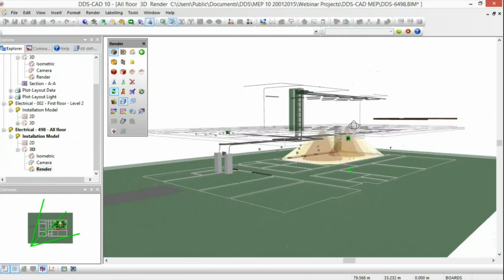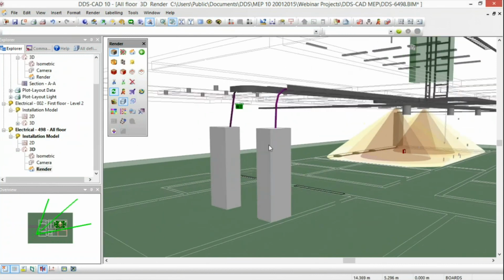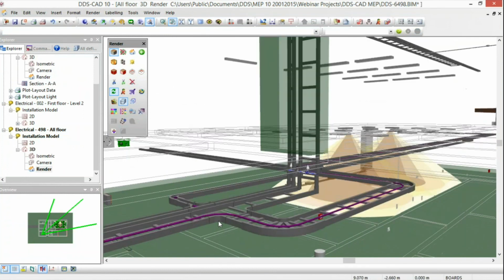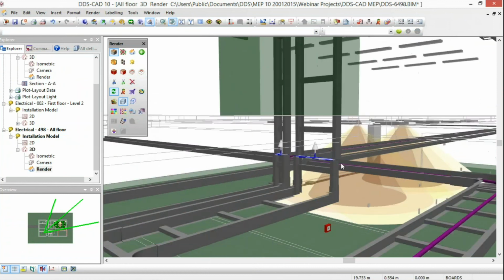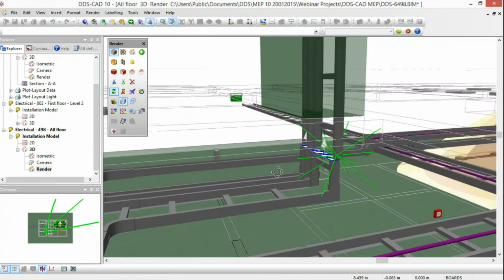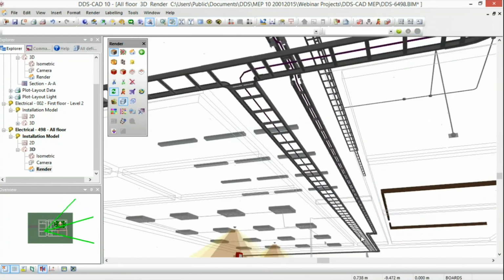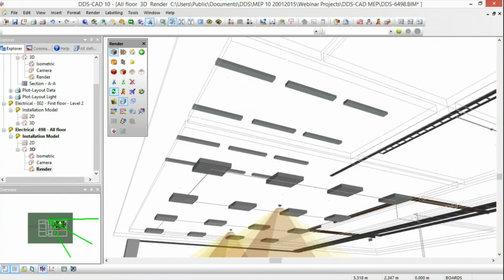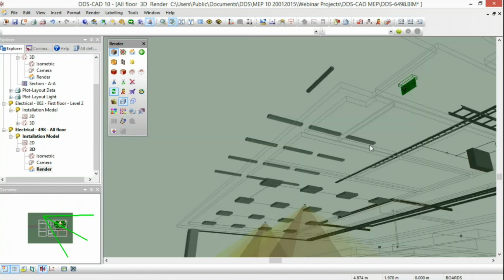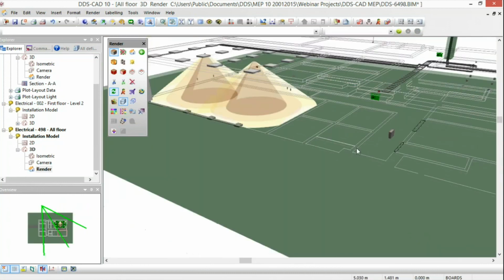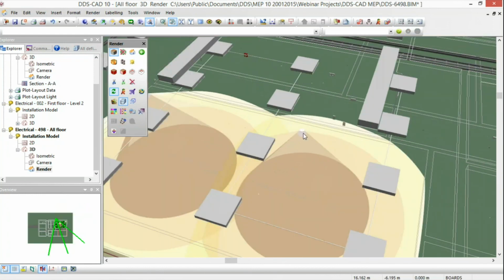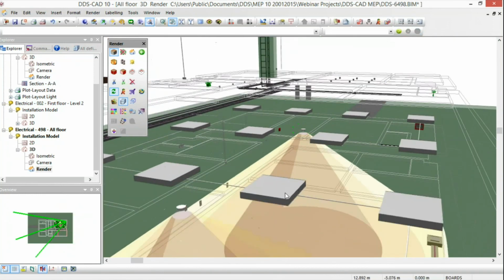that will represent all my electrical parts, starting from the distribution boards with the conduits going into the model accordingly to the cable ladder. We do have a connection of the cable ladders going to one floor and the other floor, which are connected. And if we then look into the connection of the lamp fixtures, we identified from the schema also the length of the cables, the load of the cables, and we can actually use this as one-to-one real-life relations to our plot layout.